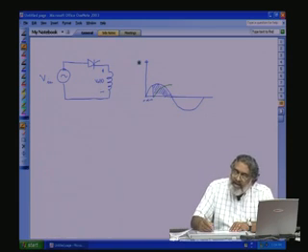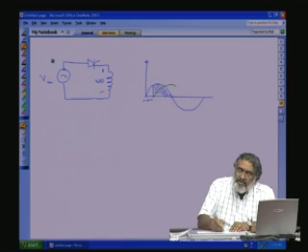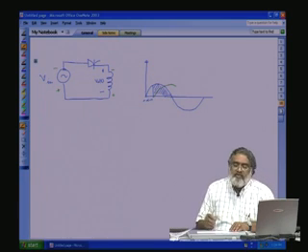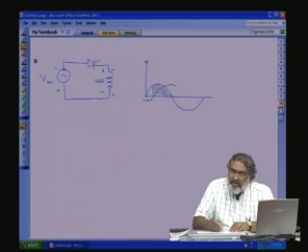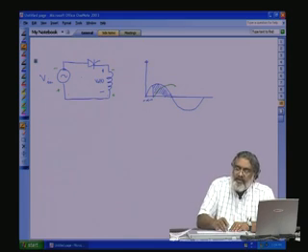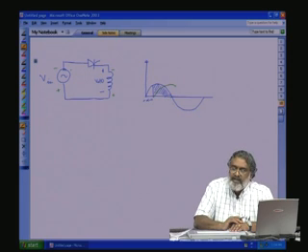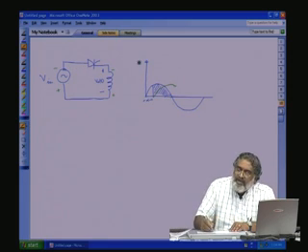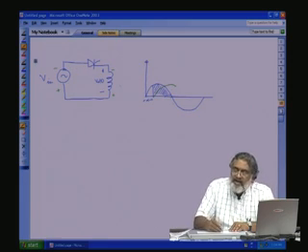At this point, the rate of change of current will go negative, so that the voltage becomes positive and negative across the inductance, opposite to the input voltage. This rate of change of current is just sufficient to forward bias the thyristor, and the current will keep on continuing from the stored energy; till the stored energy is released, the current will keep on flowing.